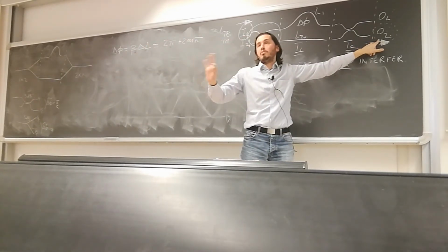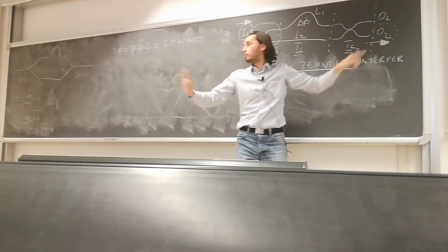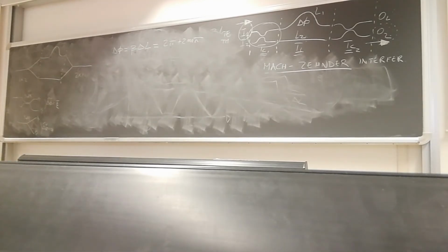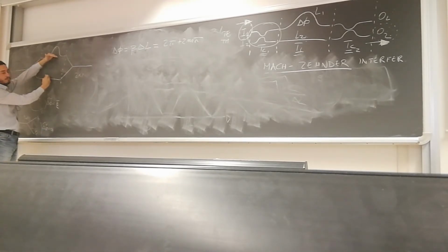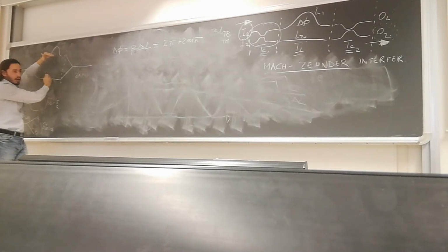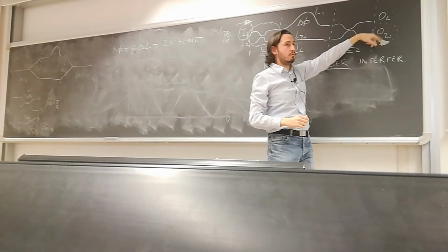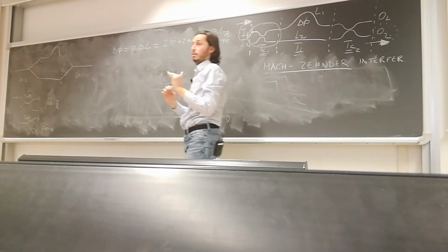You can check it mathematically. But without using the equation, the reason is that it's the total phase shift that matters. And if you have a different initial phase shift, pay attention that the phase shift that your delay lines have to introduce to send the power where you desire can be different.